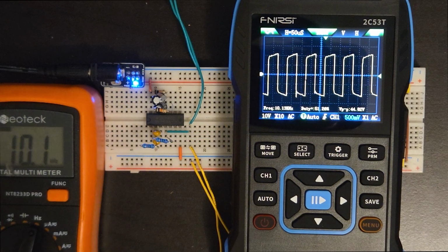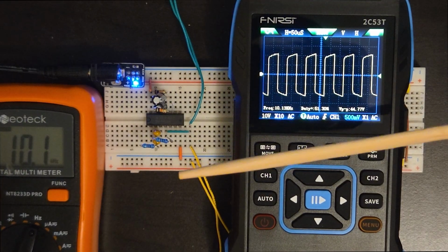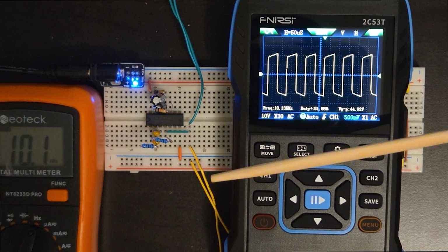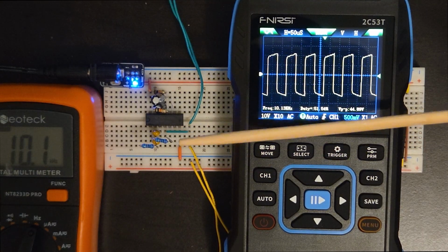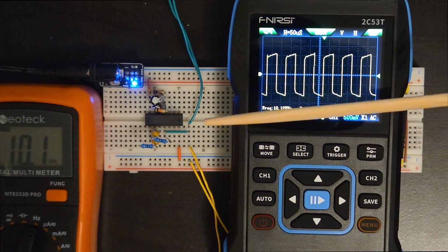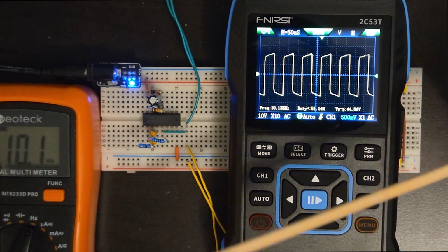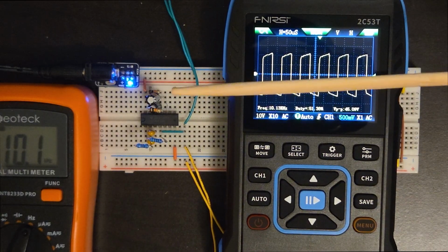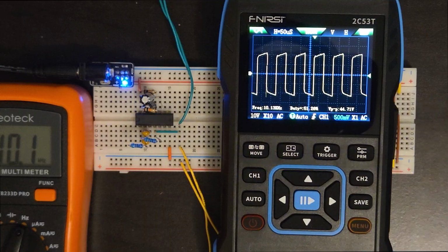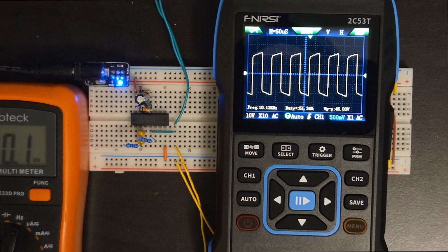And then finally, if we loop back around to our clock here, the ADC runs on every oscillation of the clock. So the conversion is fairly fast. As we mentioned, 10,000 cycles per second. So every cycle of the clock, the ADC will reference the voltage, compare it, sample it, change it, and then eventually try to get closer to that sample voltage.